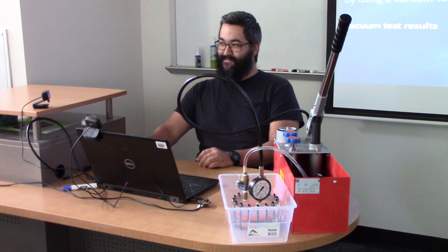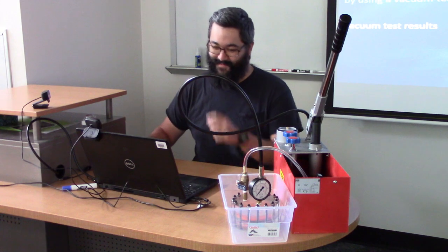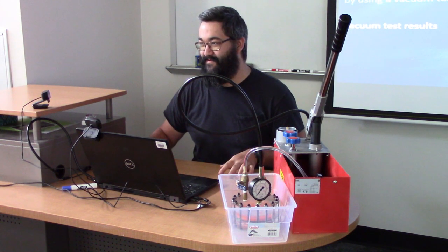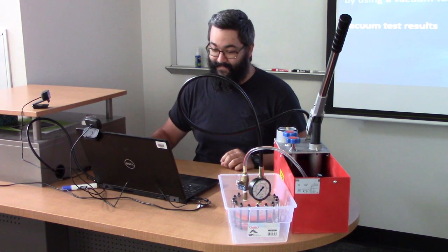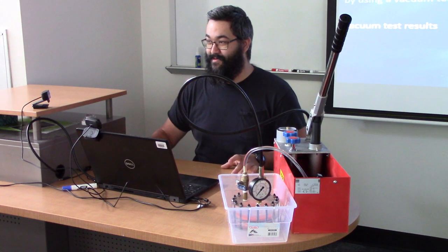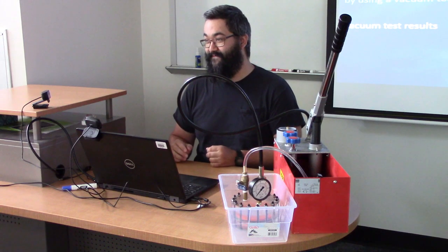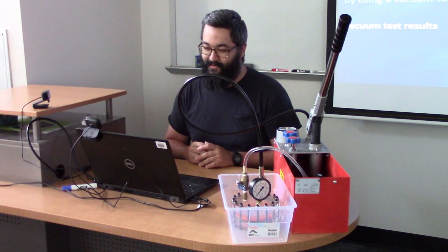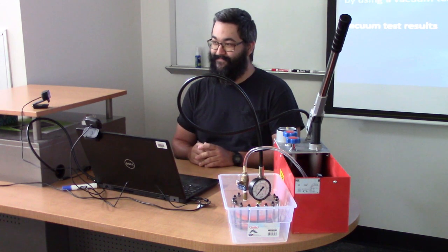Last question. Have you tried to take a picture in the microscope? No, I have not. There's no picture in here, of course, but there was a paper that I was referencing that actually added the extrusion modifier to my list of parameters to change. And they have X-ray images of the 3D printed parts. So you can actually see as they increase the extrusion modifier, the voids are shrinking to almost nothing. So it becomes literally almost a solid piece of plastic with a very high extrusion modifier.